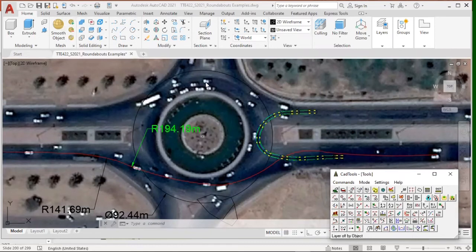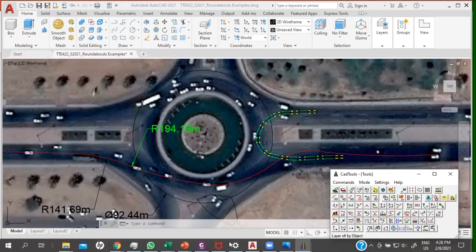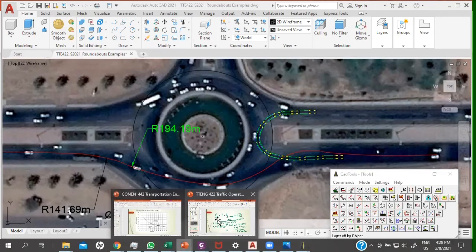There's another issue, which is basically the alignment with lanes. Okay. There's a problem with the alignment with lanes here, because you can see that you can enter, there is no real alignment for the lanes. You see the lanes going directly to that. So that's one. And also the exit. You can see it here even, that there are parts of this roundabout that are not being used by the traffic. You know what I'm talking about?